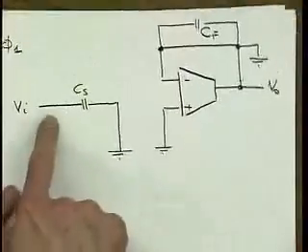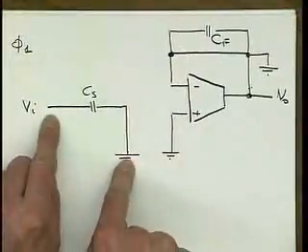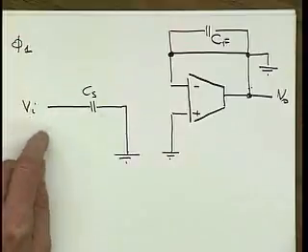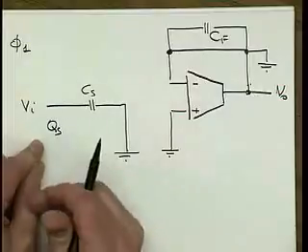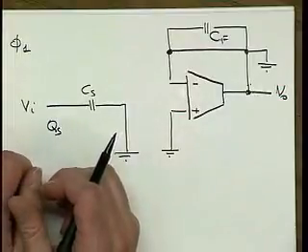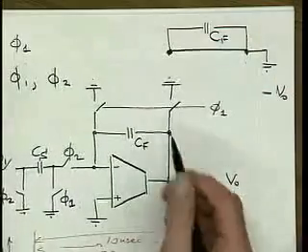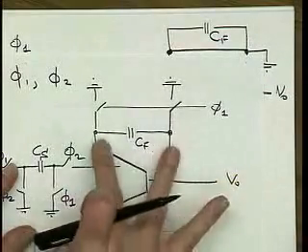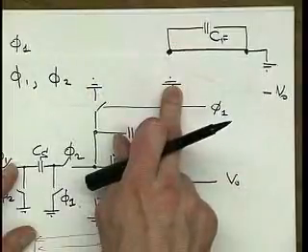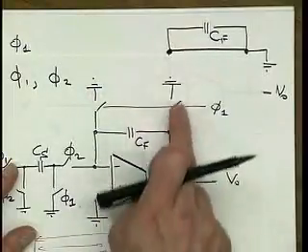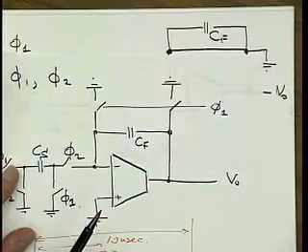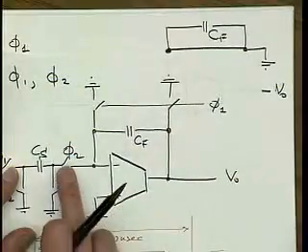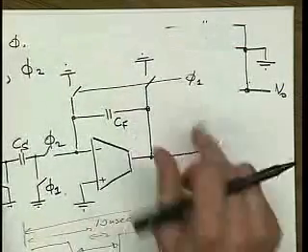Okay, so also during phase 1, we're just imprinting the voltage Vi on CS. So the charge, well, because both sides of CF are connected to ground, right? And ground is one terminal, so really it's like a short, right? It goes through 2 switches, but then it's shorted. Phi 1. Phi 2 is open, yes. This one's phi 1, yes.